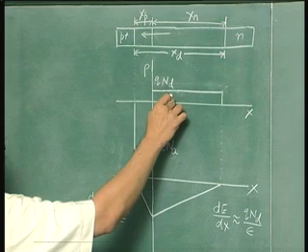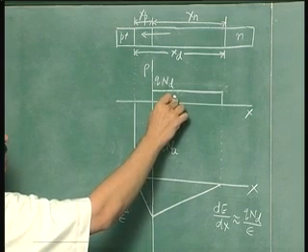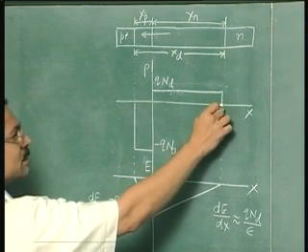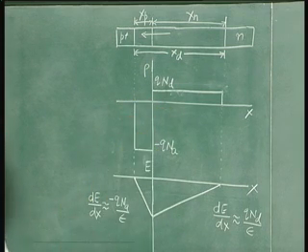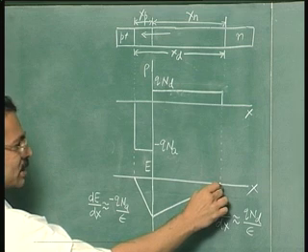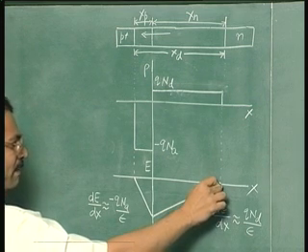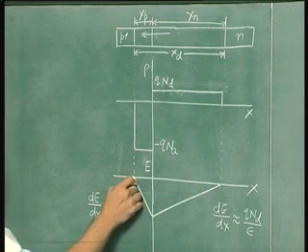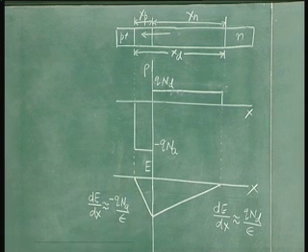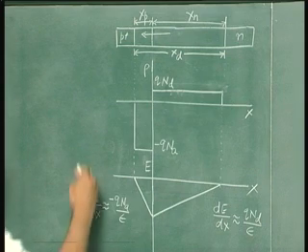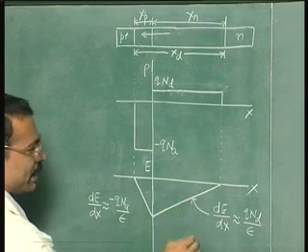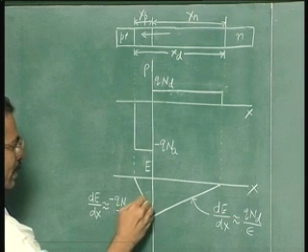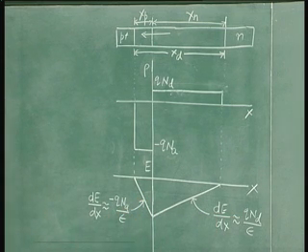So the total positive charge here, that is the area under this curve, is equal to the total negative charge, that is the area under this curve. That is why we are starting from 0 electric field at this edge and returning to 0 electric field at this edge here. This is a statement of charge neutrality. So overall the device is charge neutral. So this is dE by dx is qNd by epsilon, this is dE by dx minus qNa by epsilon.